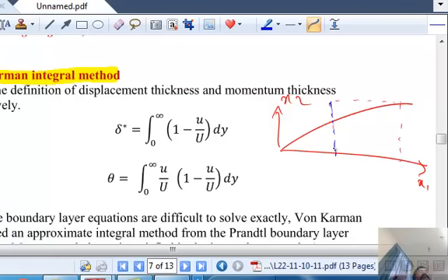I'm going to take the momentum equation and integrate from 0 to infinity in the x2 direction, and that momentum I'm going to balance against the edge. So I'm going to integrate the x1 momentum equation, use the continuity equation in there, and see whether I can develop a simpler integral equation that will tell me how the boundary layer thickness changes with x1,